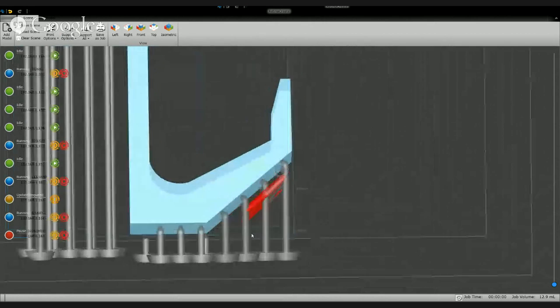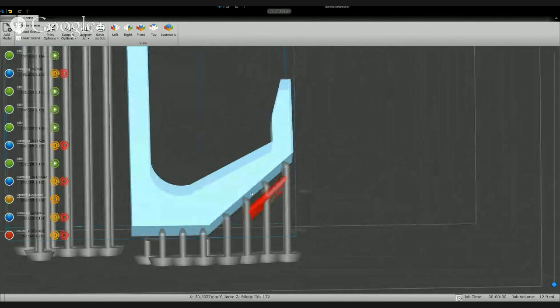They have a height, a drop-down height from the model, a distance from the model, and also there's a minimum height that the beam must be before a crossbeam is made. And so this beam is not connected with cross beams because the height of this beam is less than that 15 millimeters.